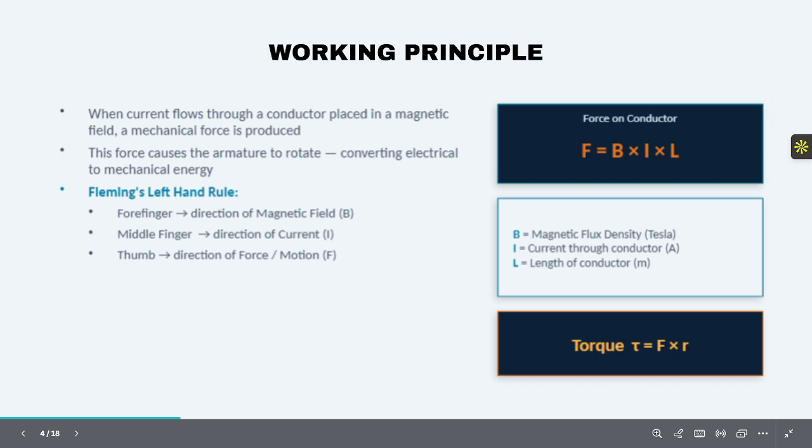Instead of giving the full voltage instantly, the microprocessor gradually increases the voltage using delay logic or stepwise control. Similarly, during stopping, voltage is reduced gradually, not suddenly. This results in smooth acceleration and deceleration of the motor.